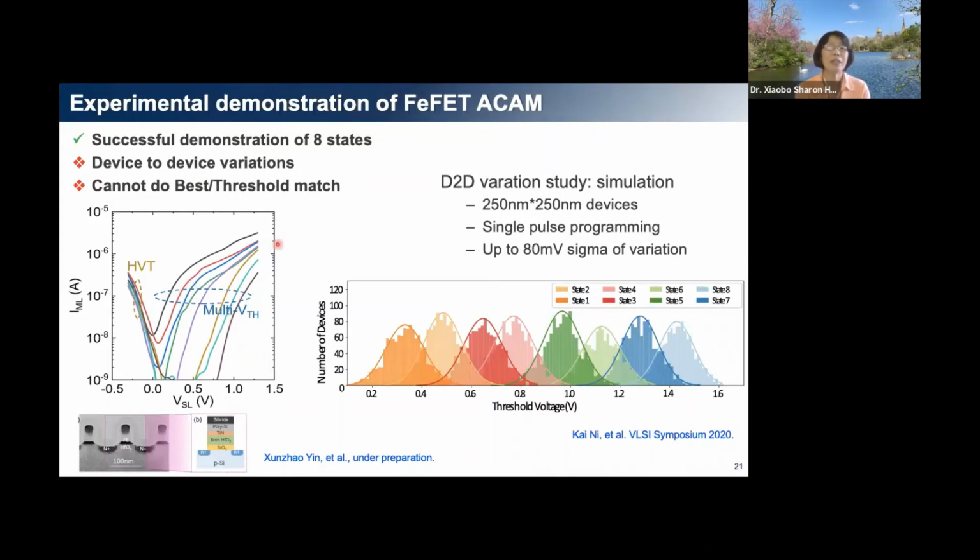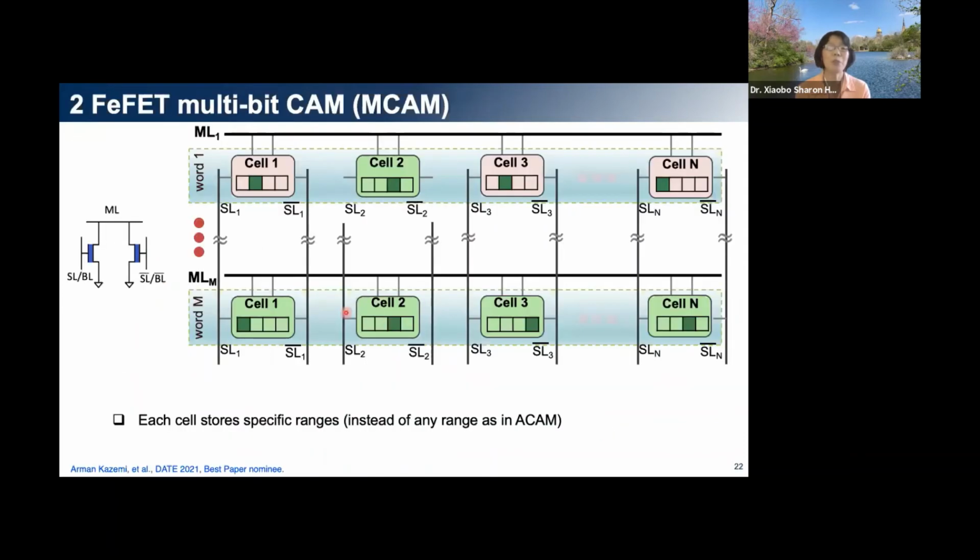Now, another challenge is that ACAM cannot really do what I showed before for the TCAM, that best or threshold match. So to address these 2 challenges, we propose another type of CAM. It's called the MultiBit CAM. So it's kind of between the ACAM and the TCAM.